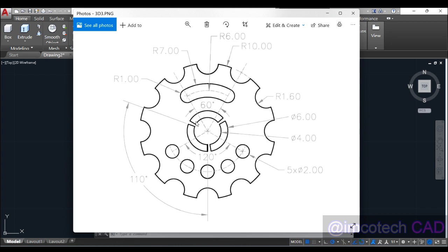Now the next thing we are going to draw is these 5 circles, 1 2 3 4 5, but definitely we just have to draw the first one and then make a copy and array for the other one. So if you have to draw it, you either draw the circle here, or draw the circle here and make an array in this direction. If you draw it here, make the array in this direction. If you should draw it here, you make the array in this direction. Very simple, right? So this particular circle was drawn concentric to this design, right?